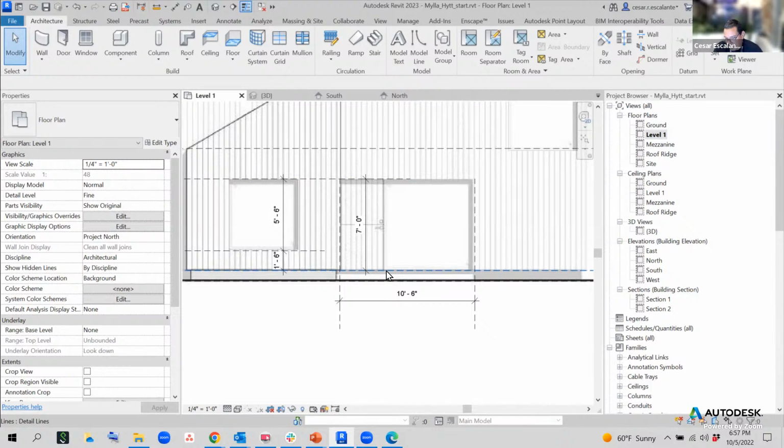So it's probably easier to build it using the custom method, and create a 3-foot door with one grid subdivision. So I'm going to create a wall that is 10.6 by 7, then create one subdivision 3 feet away from the jamb, add the mullions, swap the panel with the door, and I should be done. Easy.